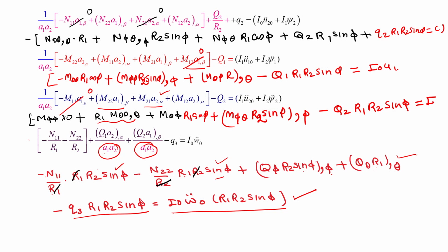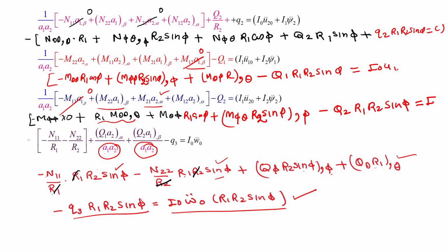So, once we get this set of equations, now the question comes, can we solve the problems? Can we get our displacements? Our aim is to find out the displacements, stresses, moments. So can we directly work with these equations? We cannot directly work with these equations because they are in stress resultant form. Whether you talk about a cylindrical shell or a complete shell or any kind of shell, we have to first convert into a primary displacement form.